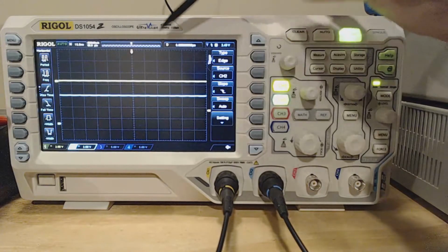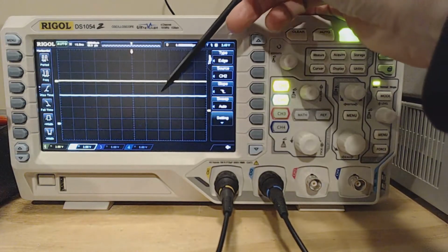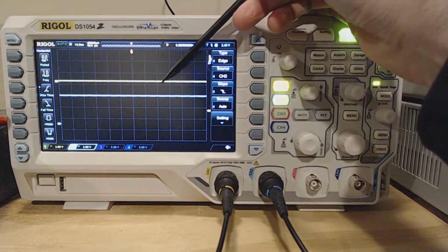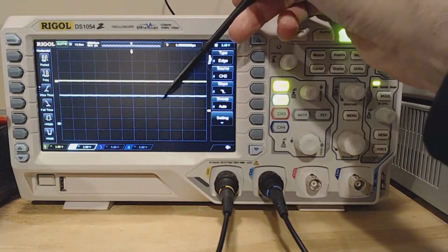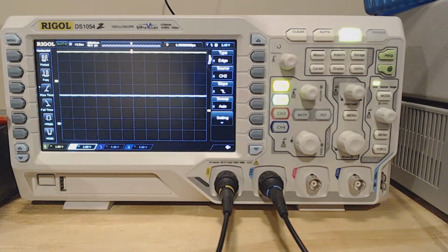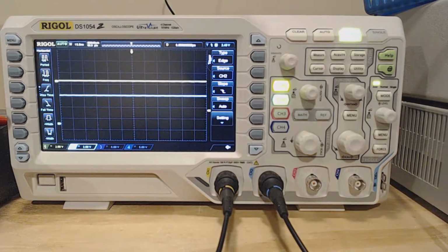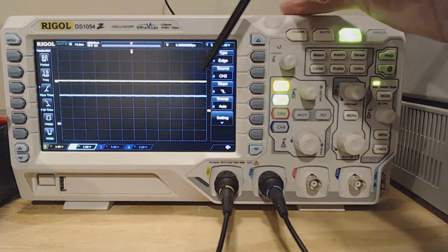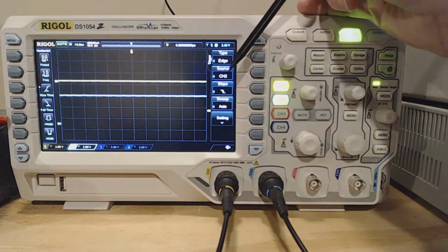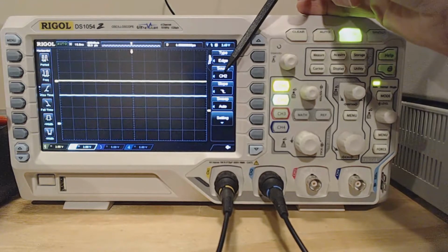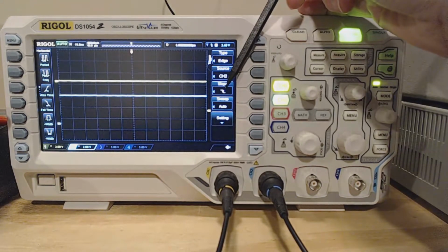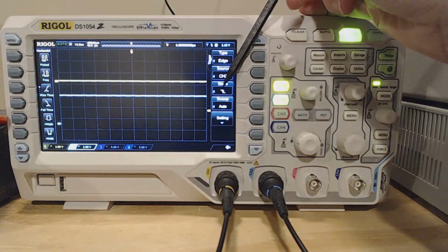All right, so here we have our signals being shown on the oscilloscope. This trace is the input signal A. It is currently low. This trace is the output signal Z. It is currently high. When I press the button, you'll notice that the input trace goes from low to high, and when I release, it goes from high to low, just like we would expect. Okay, so in order to capture the glitch, we have a trigger set up on the second channel, that's the output of the OR gate. We're going to trigger on a high to low transition, so we want to see when the output of that OR gate goes from high to low.